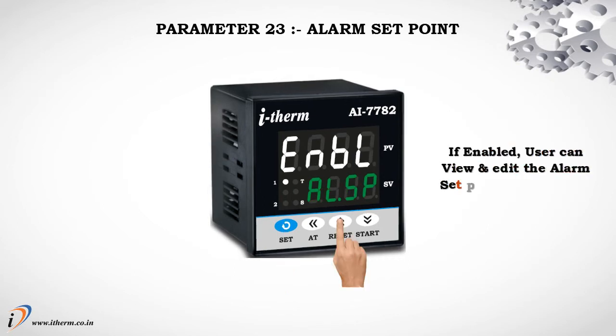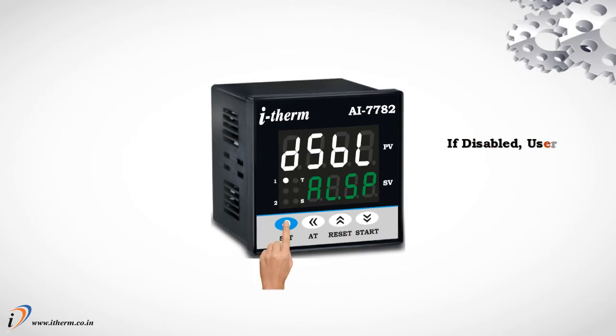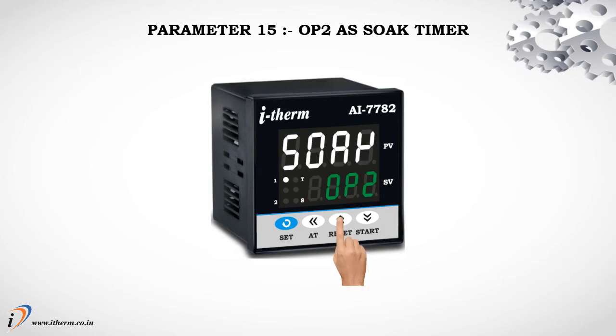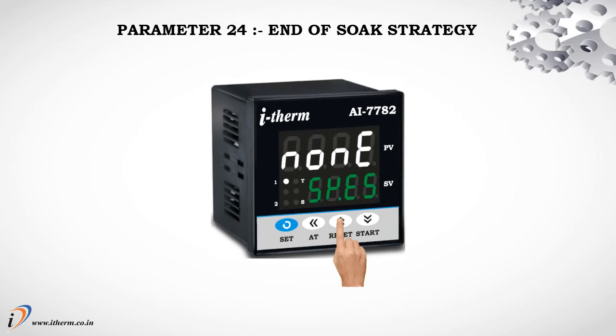Parameter 23, Alarm set point. If enabled, user can view and edit the alarm set point in user list. If disabled, user cannot view and edit the alarm set point in user list. Parameter 15, Output 2 as soak timer. Parameter 24, End of soak strategy.